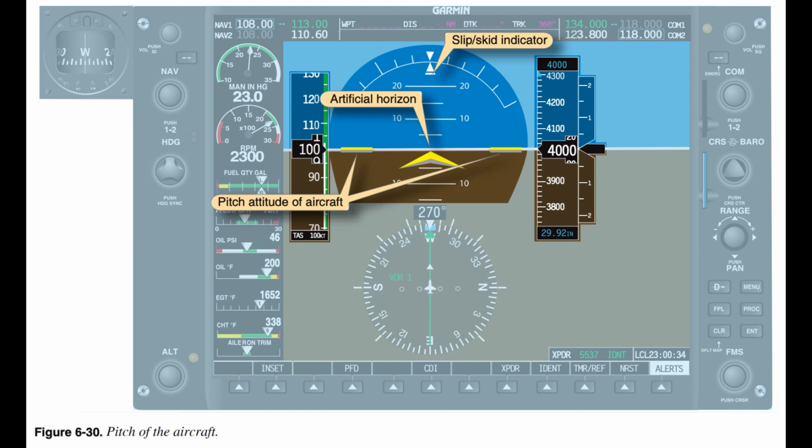The only instrument capable of depicting the aircraft attitude is the attitude indicator displayed on the PFD. The Attitude and Heading Reference System, AHRS, is the engine that drives the attitude display. The AHRS unit is capable of precisely tracking minute changes in the pitch, bank, and yaw axes, thereby making the PFD very accurate and reliable.